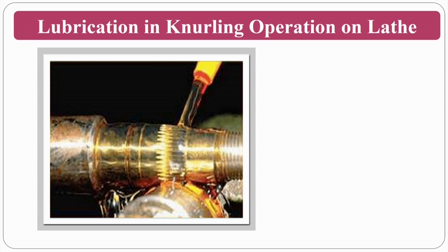The lubrication in knurling operation. The knurling operation is a very slow process. That's why you always go for mineral oil based cutting fluids, where the lubrication is dominating. You can also go for emulsions, but you can give preference to mineral oil.